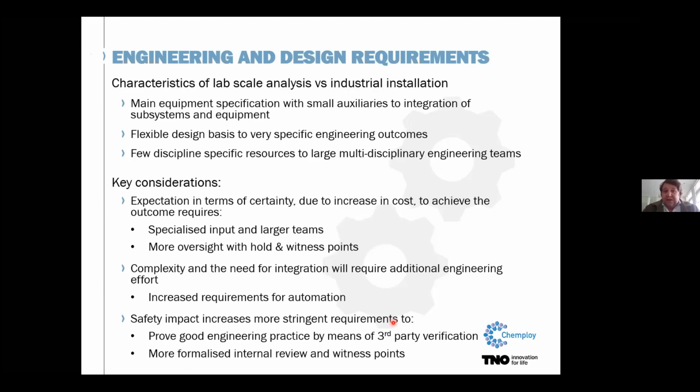And to that, of course, what you'll then find is that you need to show more and more. As you continue building these larger units, there's an expectation that you prove your good engineering practice by means of third-party verification. An example, again, if looking at something like the pressure equipment directives, what you'll find is that for smaller volume vessels, for smaller units, they will typically indicate that you comply to best design practice, but as you move to the larger units or larger volume vessels, the expectation is that you need to get inspectors in, they need to certify the design and review and make sure that everything is okay.